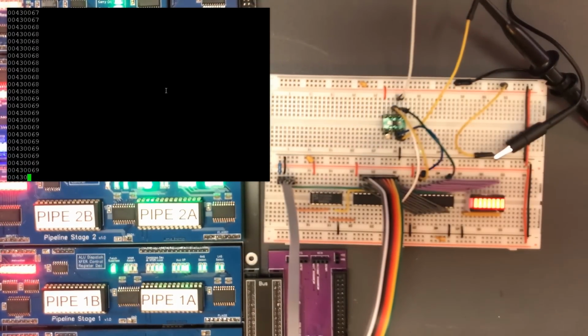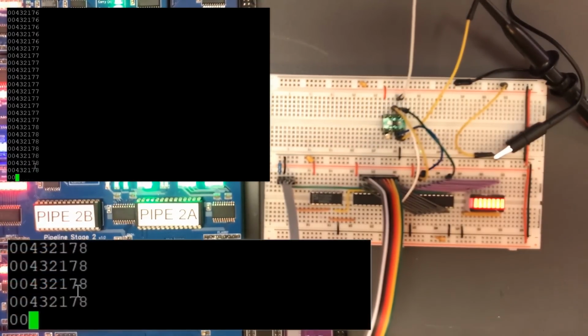Okay, that looks quite promising. So this column's definitely ticking up in seconds. So this would be 43 minutes, and I'm at 52 minutes recording, which would be about right for when I actually put power to the RTC chip for the first time. I think that's working.